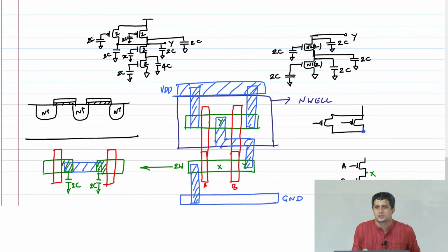For example, even in the PMOS, the diffusion is shared. If you look at this, the diffusion is shorted here. The difference is I need to put a metal contact here. Because I need to put a metal contact, I need spacing, and therefore I have to keep the transistors far apart, and each transistor will contribute to its capacitance. So the golden rule is: if it is an uncontacted shared diffusion, then you don't double count the capacitance.